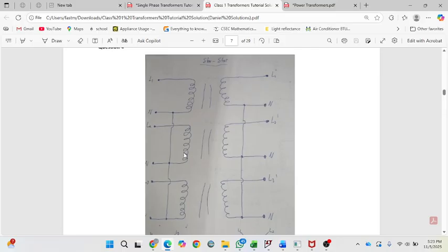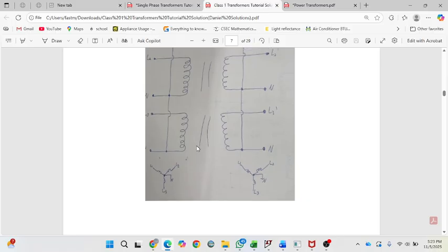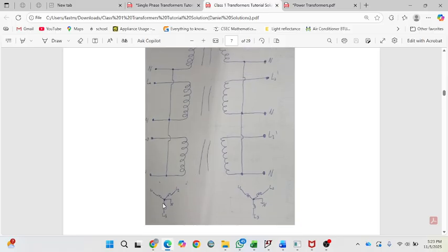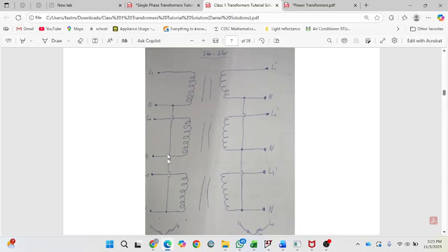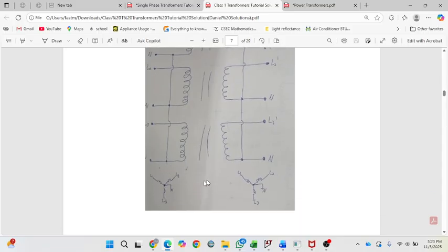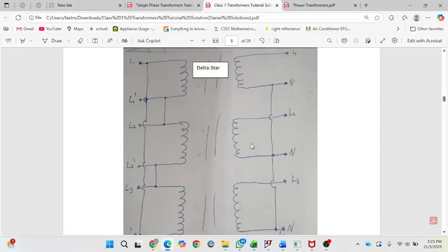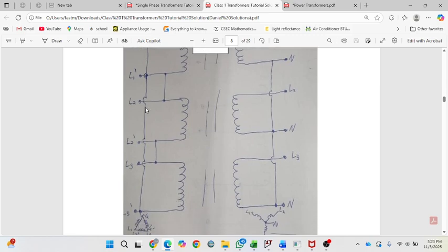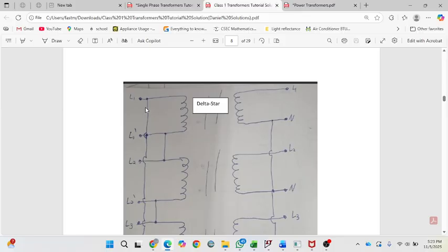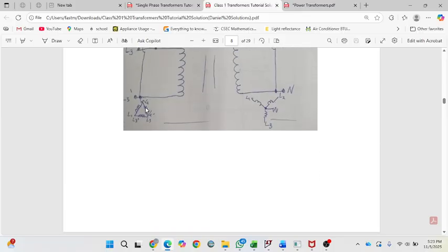Each of the coils, you have three coils because it's a three-phase system. For a star, you have to draw any commons together, with L1, L2, and L3 coming in. And the delta is basically everything in a loop. Once you start one through the loop, connect to the next one, and the next one, then go straight back up to the top. It's like a circle for the delta. So you can look through the patterns and see.